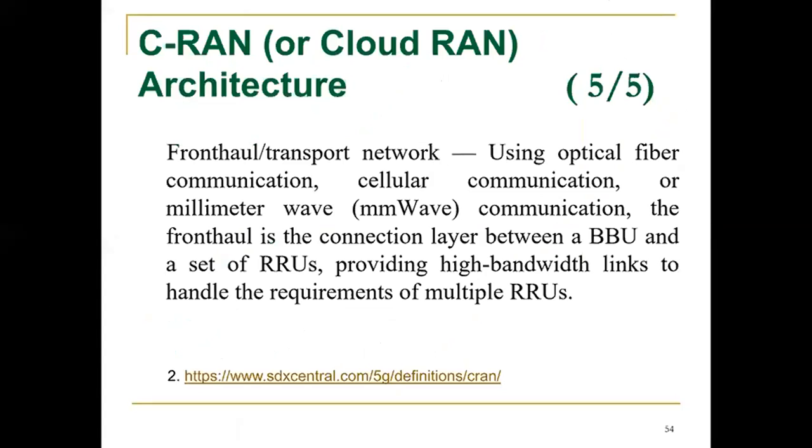And the base station is under the load of a number of users who are using different applications. Somebody is using WhatsApp, someone is using a Zoom session, somebody is playing real-time games. So all these different data are received at the base stations, and the base stations receive the signals using the radio resource unit. They do not have baseband units. Rather, they transmit all the analog signal from the radio resource unit, digitize it, and send it to far-flung areas using the transportation system that is called the fronthaul.